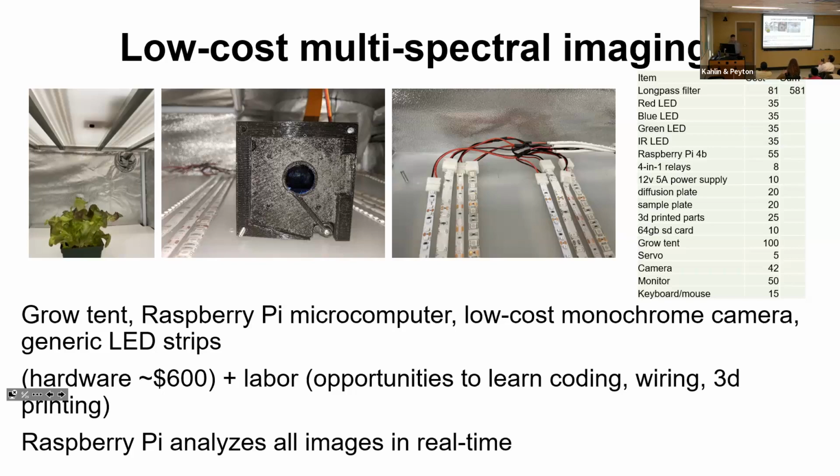There were some wiring lessons learned. We were a little too liberal with our use of quick connects, and we ended up having intermittent connection issues for a while, so we had to resolder the whole thing. I've rewired this entire thing twice, but it works now. So you learn how to code, you learn how to wire all of these parts. And this part right here, that little arm that holds the filter, and that camera module, those are all 3D printed parts.